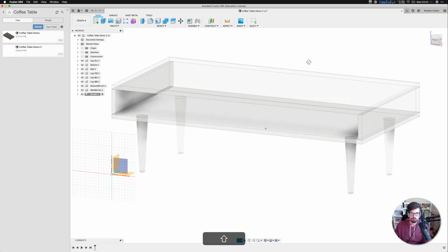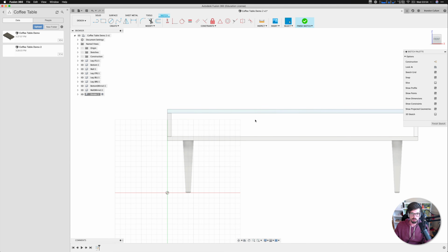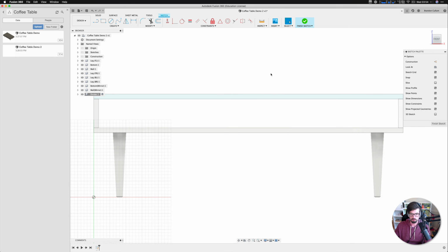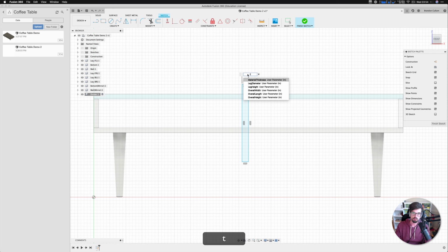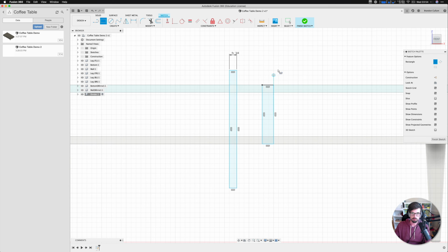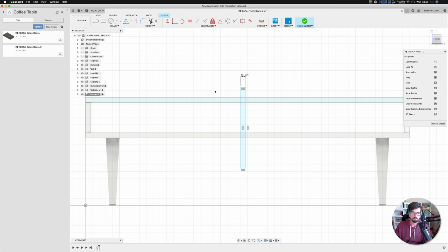I'm going to sketch. So you can see I'm selecting the front face, and now I'm on the front face, and you can draw here. So we could do this. Again, this is going to be the thickness. When you're drawing, you can just go ahead and attach stuff, so it's already going to do these constraints that I'm going to do here in a minute. You can see that's already coincident, but I do that just in case you missed it and you need to connect it.